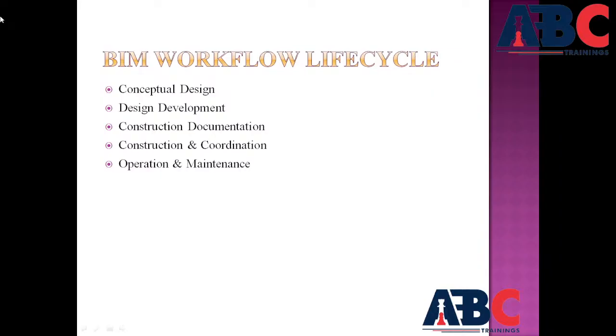Next one is construction documentation. At this stage, the BIM model serves as the source of all the construction drawings and specifications. Because BIM is data driven, every 2D drawing, plan, section, and elevation is generated automatically from the 3D model.